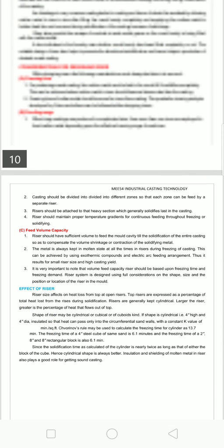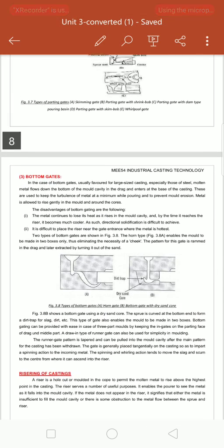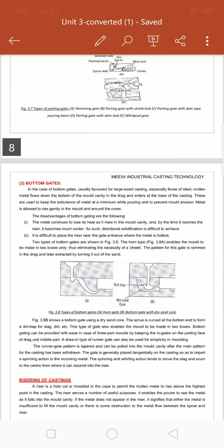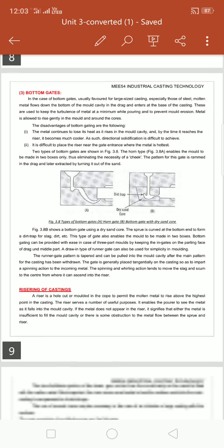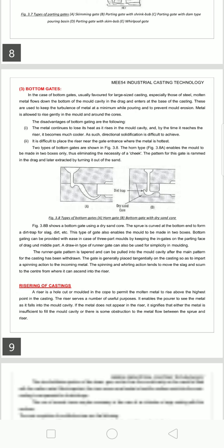Sea coal in powder form improves surface finish of the casting, added up to 8% by weight. Pitch, a derivative of soft coal, improves surface finish and hot strength, added up to 2%. Wood flour, finely ground wood powder, is used to minimize sand expansion and improve collapsibility, added up to 2%. Silica flour, up to 35%, especially in steel casting, improves hot strength, increases density, and prevents metal penetration.